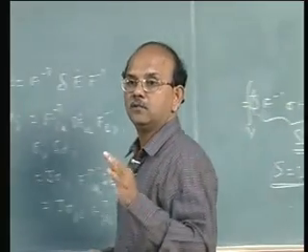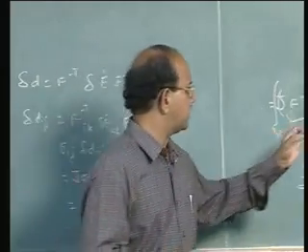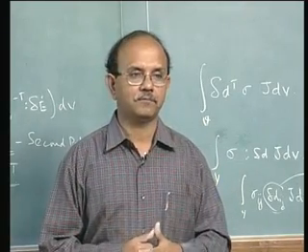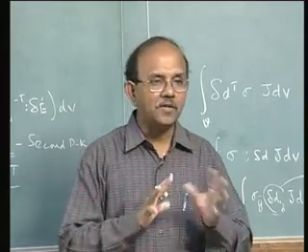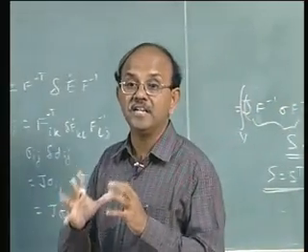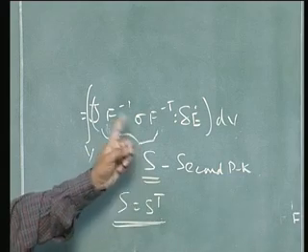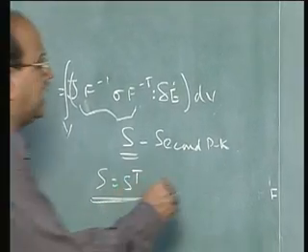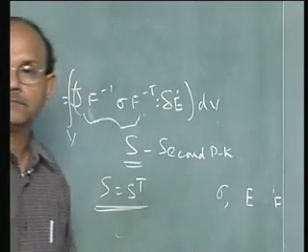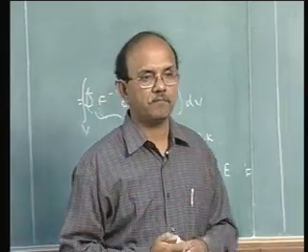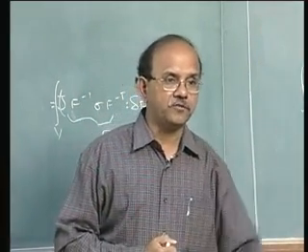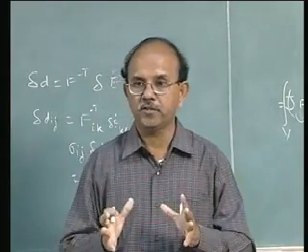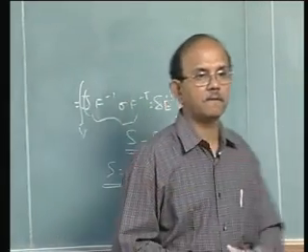And you will see that there are conjugates for every stress or every strain. For example, if you take P, it has its conjugate, say F dot. In other words, what is conjugate? What we mean to say is that whatever be the stress measure and the strain measure we use, there should not be any change in the scalar. In fact, we arrived at the second Piola-Kirchhoff stress from that concept. So we are totally wrong if I say that I will take sigma and I will take E and do my problem. This is not correct. They are not conjugate measures. Is that clear? So though you have a number of stress measures and strain measures, whenever you do a problem, you have to be careful in selecting one and the other in such a fashion that they go together as far as this is concerned.